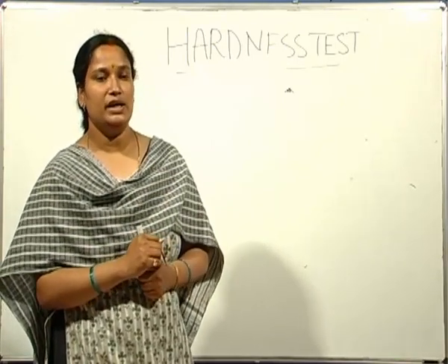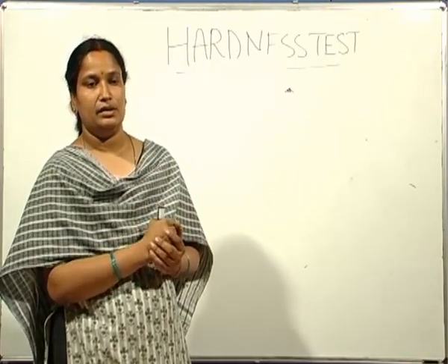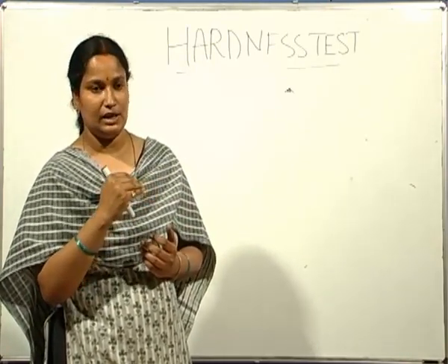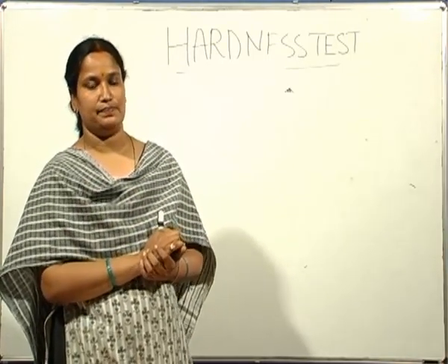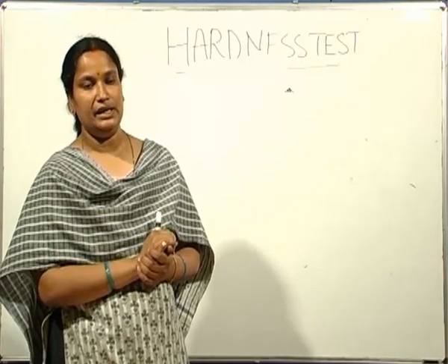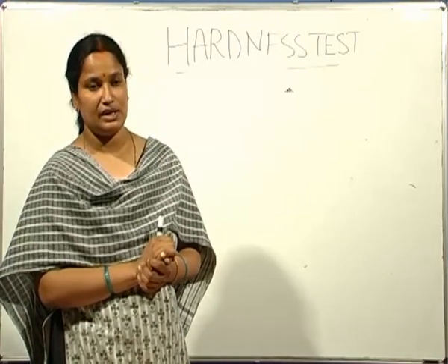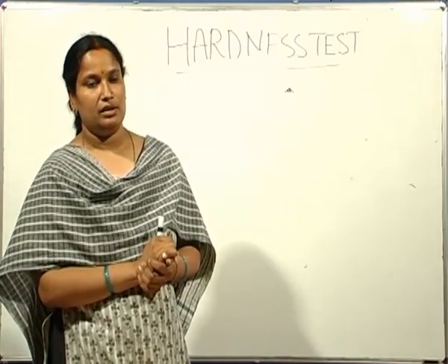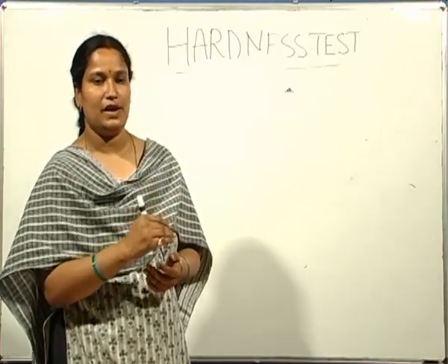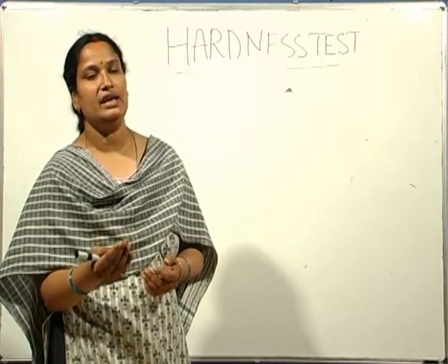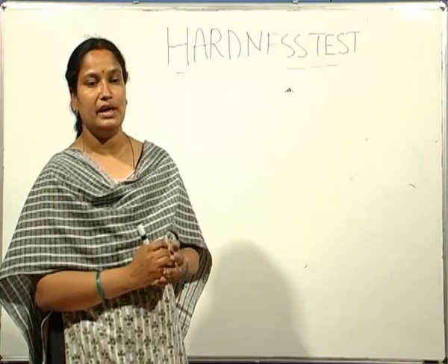And for the case of annealed metals, from Meyer's law, it is seen that with increase in load, the hardness value increases, indicating that the material undergoes strain hardening. Whereas for the case of Brinell, it shows that for annealed metals, the hardness values first increase and again decrease, indicating material softening. Again, this is incorrect.